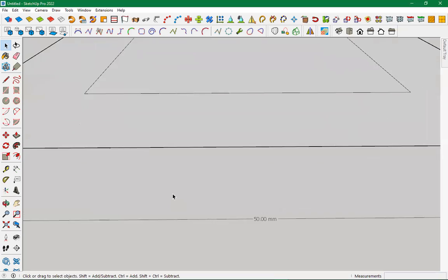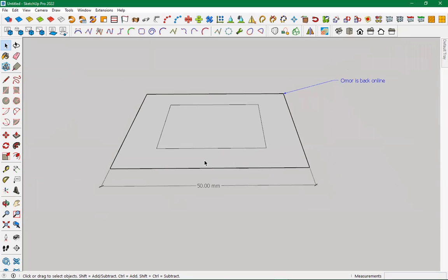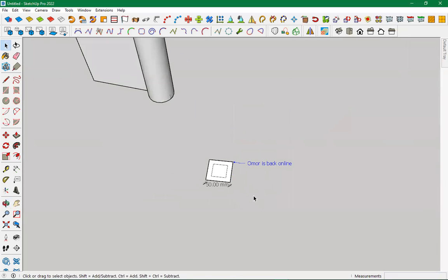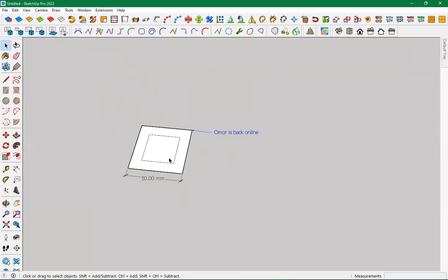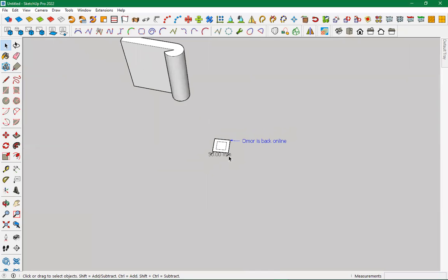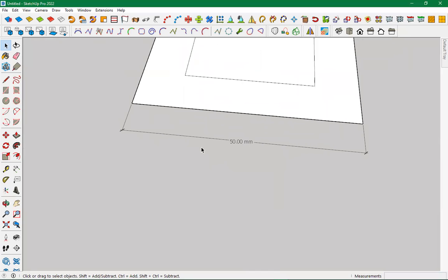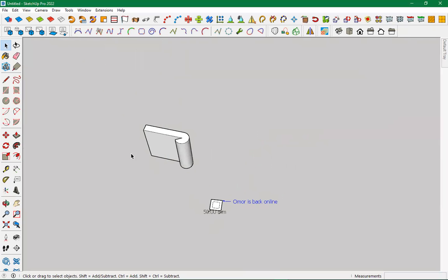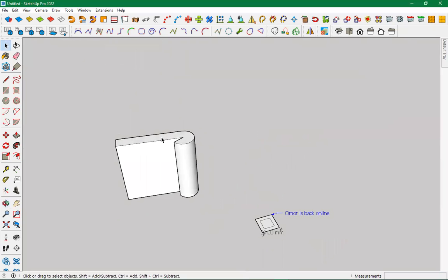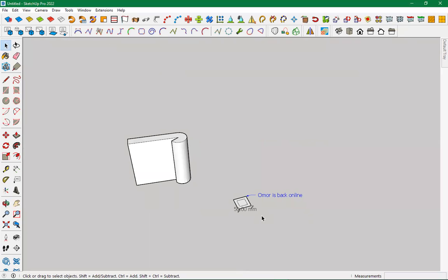You can zoom to wherever the cursor is pointing, that's where you're zooming towards. And if you notice, the dimension here is annotative. So you see it goes like so. So you see why basic understanding of AutoCAD is very important for other CAD softwares.